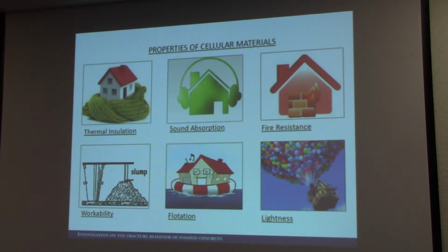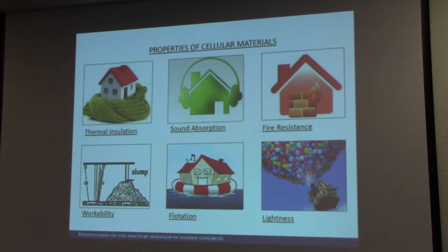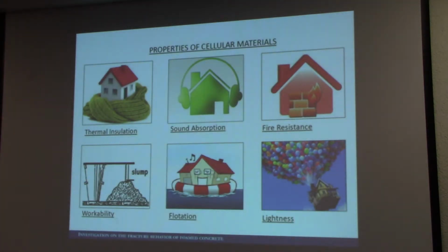In particular, these variants of concrete materials have different advantages in comparison with normal weight concrete, ordinary concrete, in particular better thermal insulation properties and acoustic absorption, fire resistance, good workability, and obviously lightweight properties that make them particularly effective for realization, for example, in infill panels or non-structural partition walls at the very low density ranges.